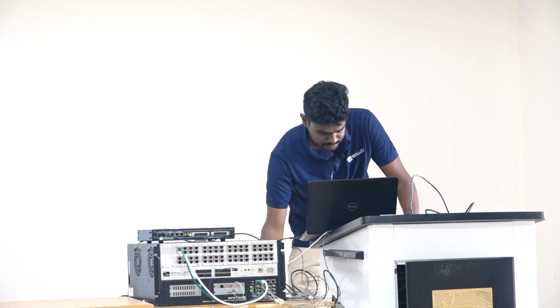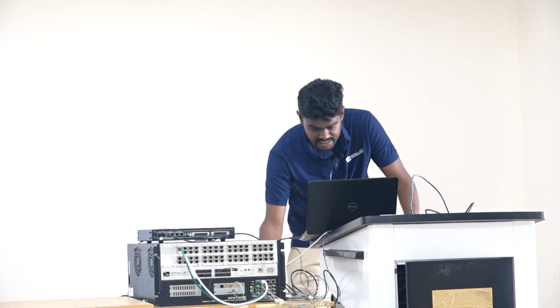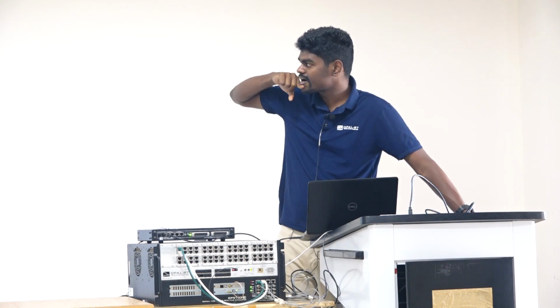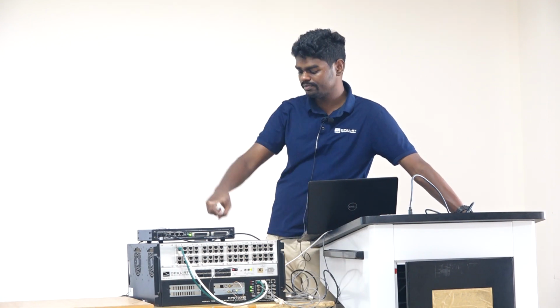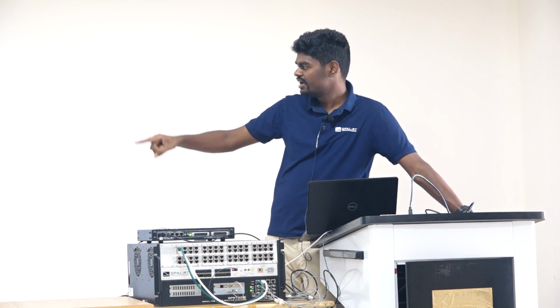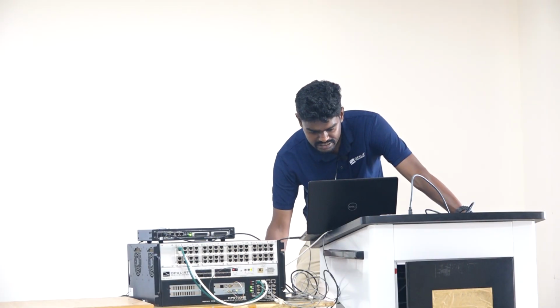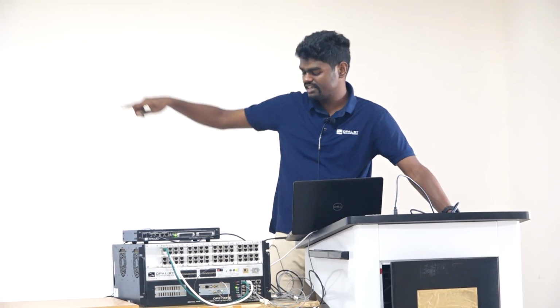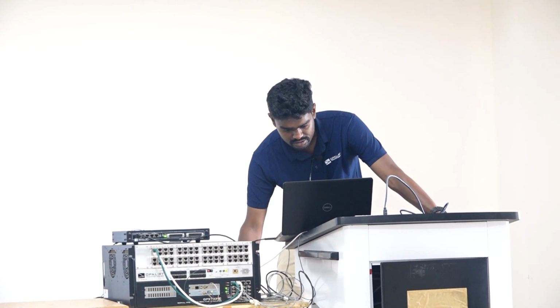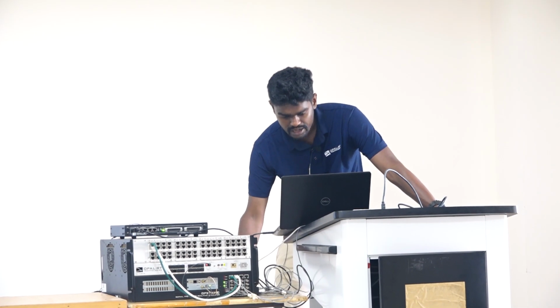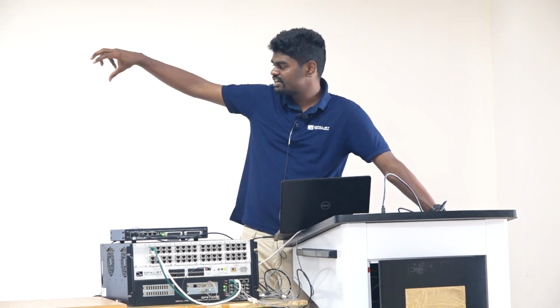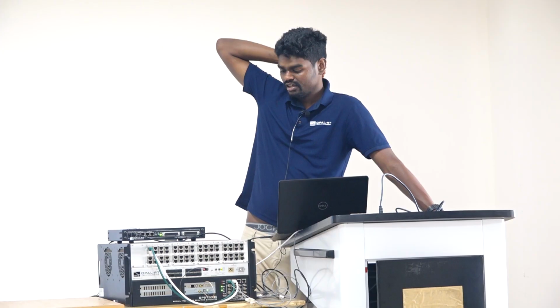You can see here I have a digital in block. This block will read the PWM generated by the external controller, and that is fed to the inverter inside. Inside the subsystem you have the inverter, and you can see all the 6 PWMs are taken from the digital input and fed into the inverter.